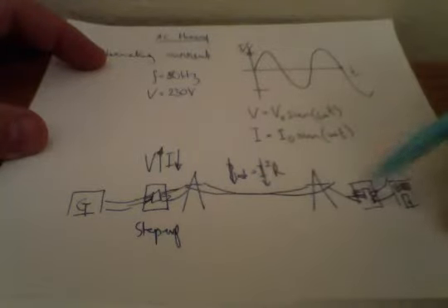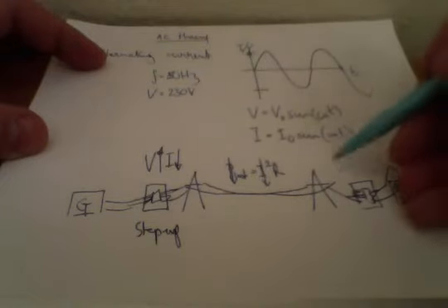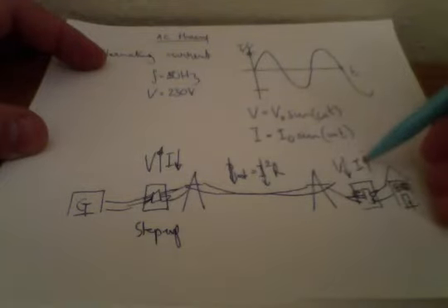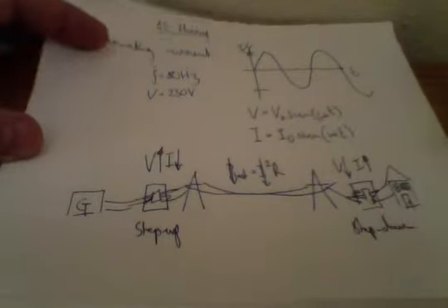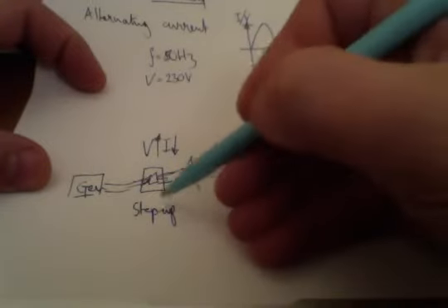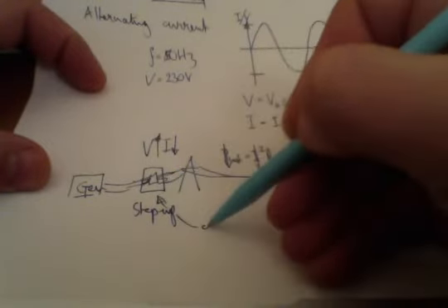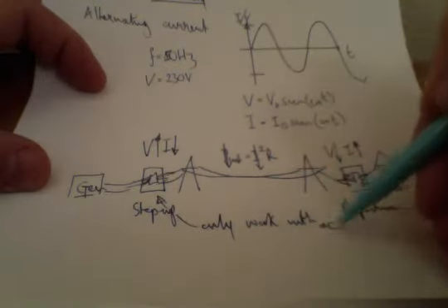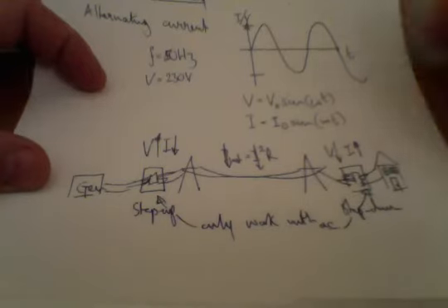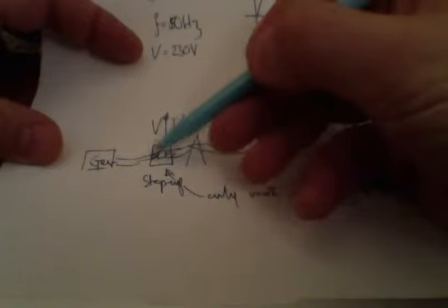And when that gets through to our homes, of course, you need the opposite to take place, because you don't want to take through a huge voltage into your home. So you step down the voltage and up the current again in a step down transformer. So, why AC? Well, transformers only work with AC, alternating current. And again, there's a whole other video as to why that is the case, but essentially it's because you need a changing magnetic field in order to cause induction from one coil to the next.